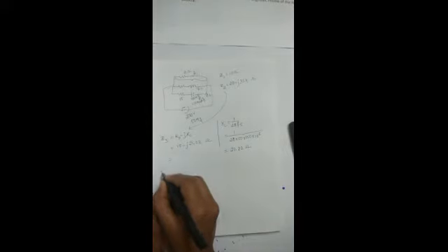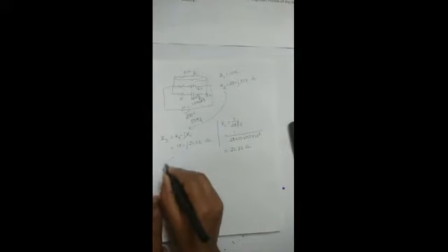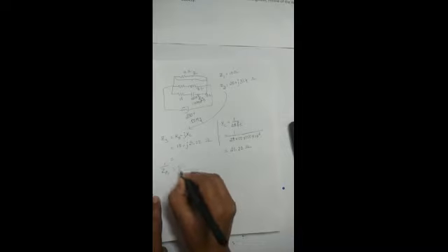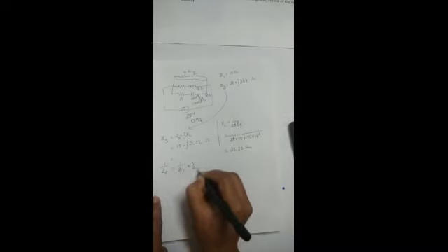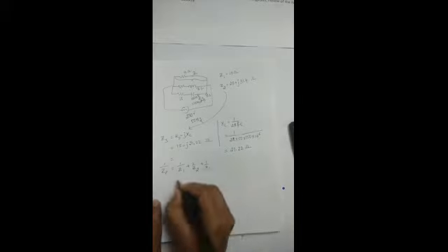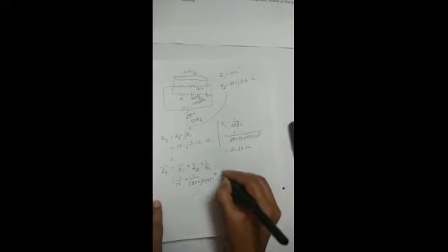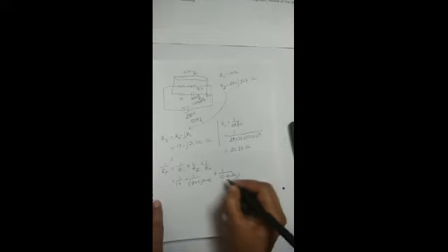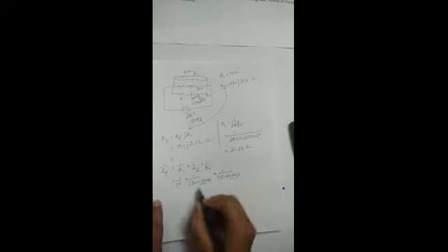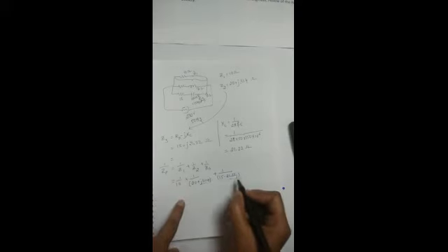So therefore total impedance ZP is given by 1 divided by ZP is equal to 1 by Z1 plus 1 by Z2 plus 1 by Z3. So 1 by Z1 is 1 by 10, plus 1 by Z2 is, in bracket, 20 plus J 31.4, plus 1 divided by the third one, 15 minus 21.22 J. Both are the same, you can write J first or last. Now this one we need to solve.